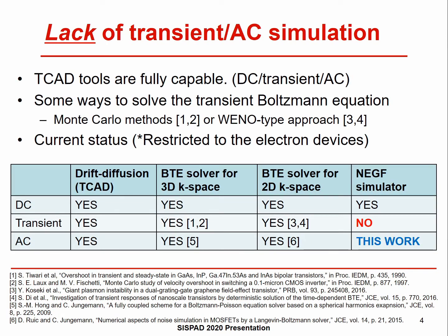However, in most cases, the NEGF technique has been applied only to the DC steady-state simulation. It is difficult to find transient and AC small signal simulation results for semiconductor devices. Of course, we may find some works in the physics journals, but those works are seldom related with the conventional electron devices. Unfortunately, recent theoretical advances have not been applied to the electron devices.